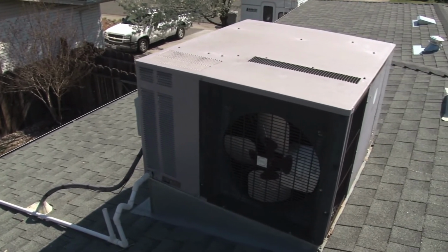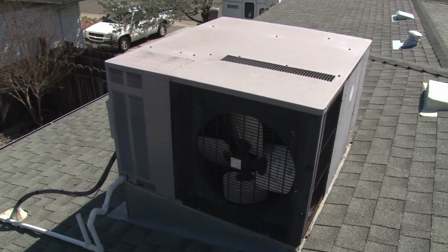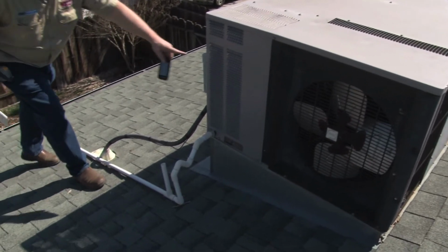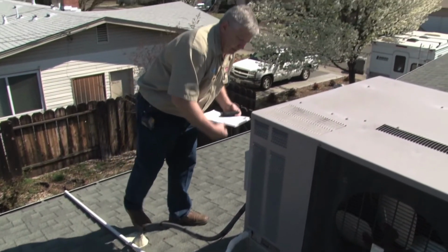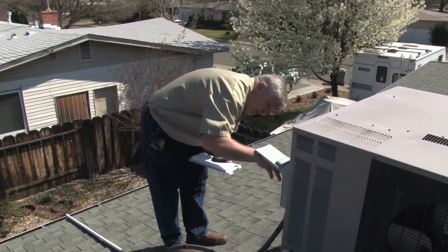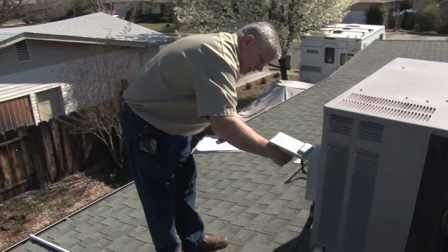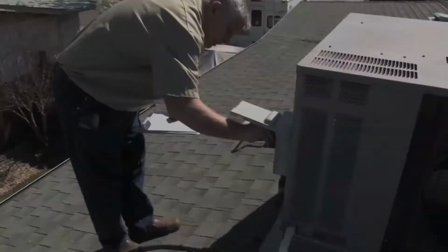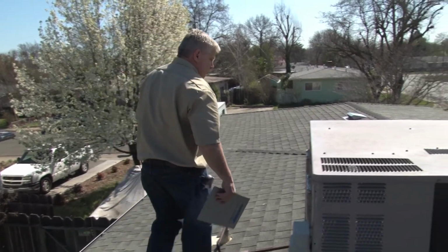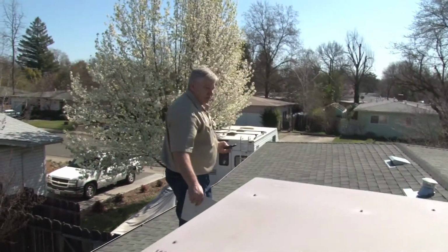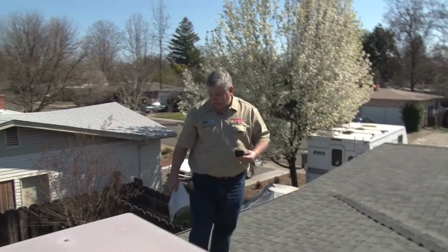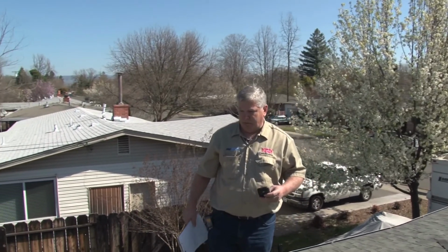The condensate is done fairly well. Has a fused electrical disconnect here on the side of the unit. And we want to make sure that that's adequately sized for the equipment. So as I pull this out, I'm going to notice that this is a 30 amp fuse, and we'll step over here and see what size the unit actually requires. The gas line is run over the roof for a little bit of a distance. That's not bad. It'll work fine for us.